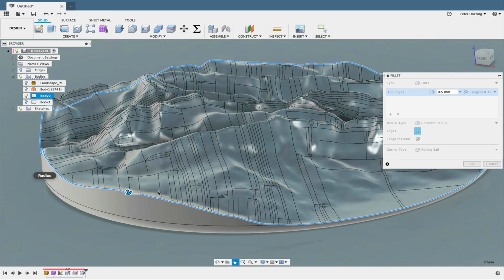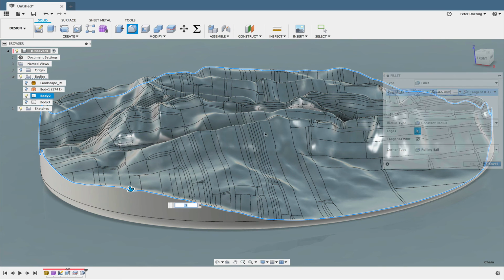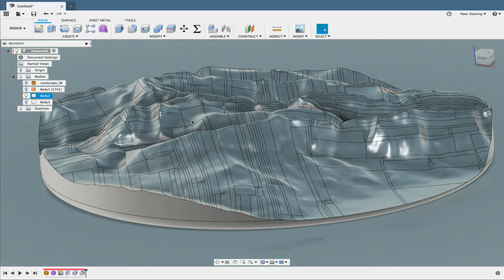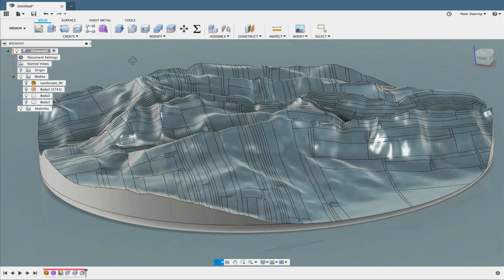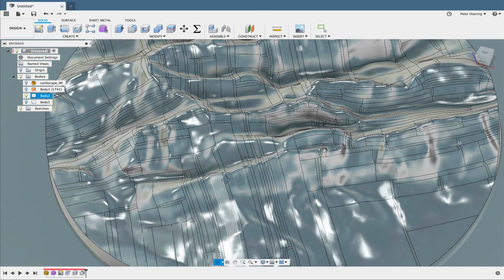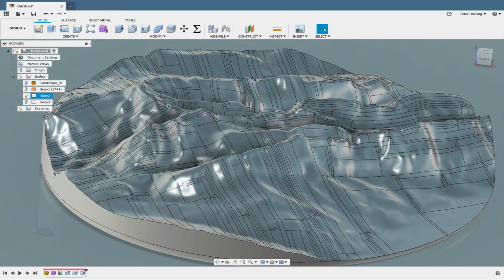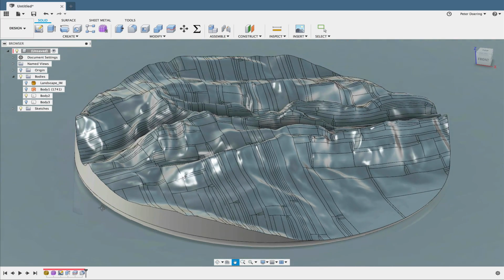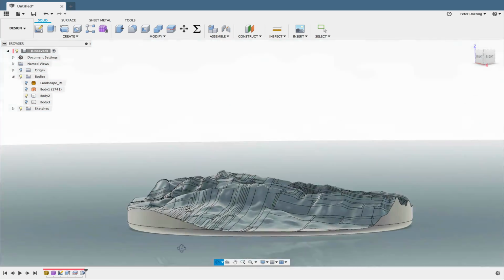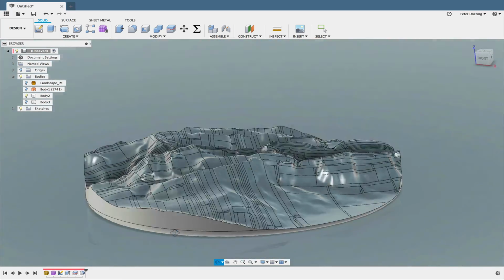So there are two things that in the solid modeling area probably won't work with these sorts of surfaces created from STLs. One of them is shelling. That almost always fails unless the surface is less detailed than this surface, and surface offset and filleting. That is very often going to fail. But other than that, you can use all the solid modeling tools that are available and work with these surfaces.